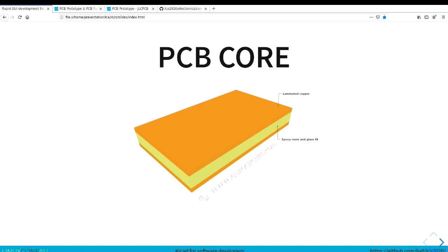We are going to do a 2-layer design, which means we have 2 layers of copper, one on the top, one on the bottom of this fiberglass core. You can get 4-layer, 6-layer, 8-layer. 4 layers is quite common. The manufacturers claim that they can do 50 layers these days. For some reason, it would be very expensive. KiCad can support 32 layers, I believe. Ballpark, it costs you about $100 US to add a pair of layers in small quantities.